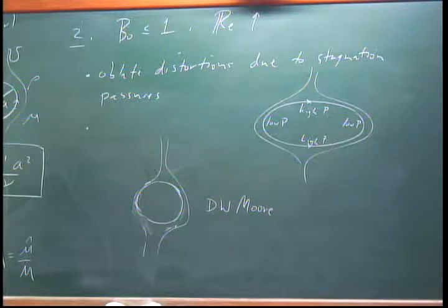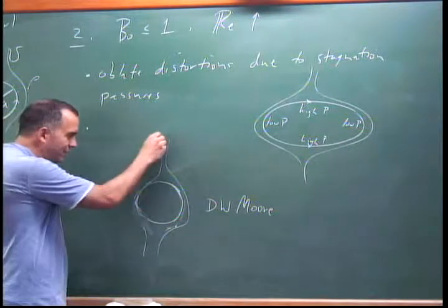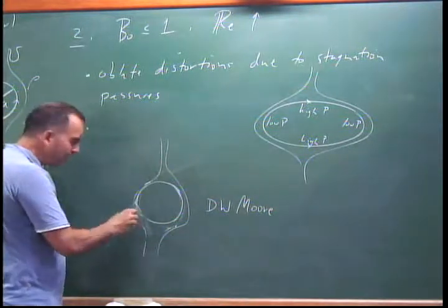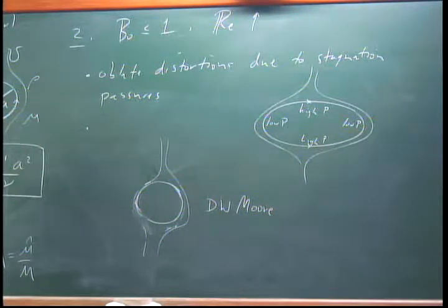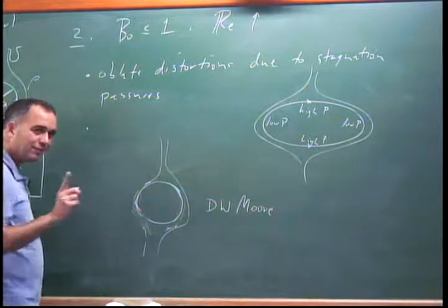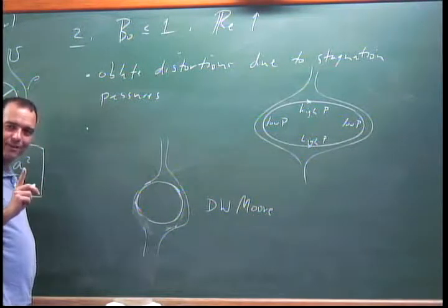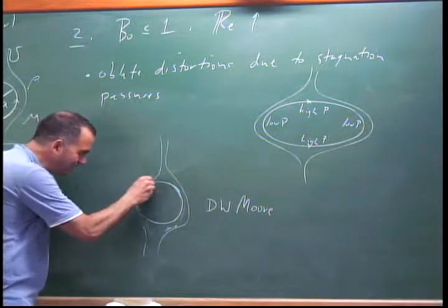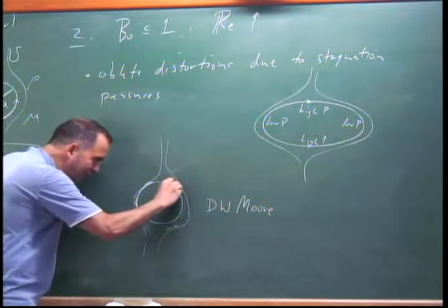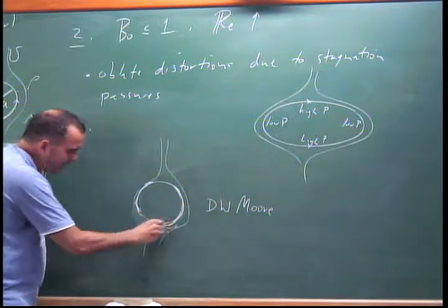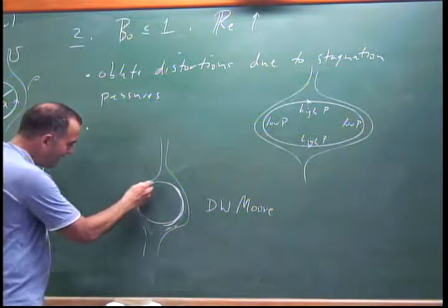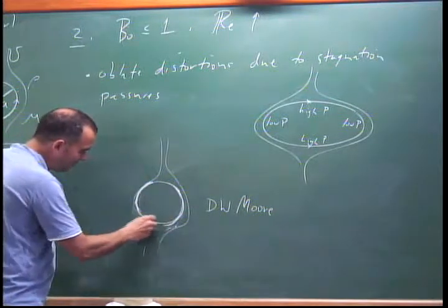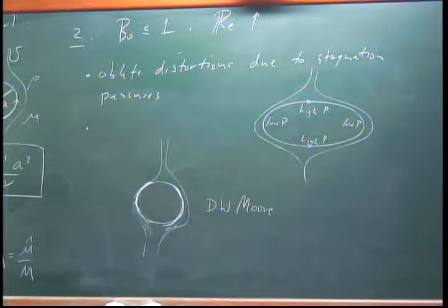You'd think it'd be better, right? You think potential flow, but if you actually calculate the potential flow around a sphere, it doesn't satisfy the free slip boundary condition. That is to say, the tangential stress at the surface of the bubble is not zero, and so again you need a boundary layer. You have a viscous boundary layer in order to satisfy the zero tangential stress boundary condition. You calculate the dissipation in that boundary layer, and that's what gives you the drag on the bubble.